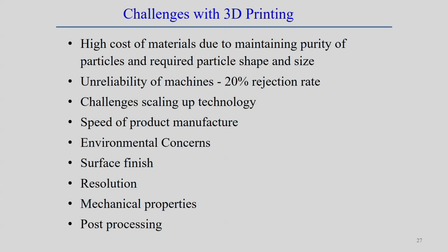For a very small component size, we can achieve very good surface roughness, and that amount of surface roughness may be sufficient if the component size is very small. But when we try to produce a much bigger component, it may not be very economical using this laser based or electron beam based metal printing technology. When large volume deposition is required, arc based additive manufacturing technology may be more suitable.